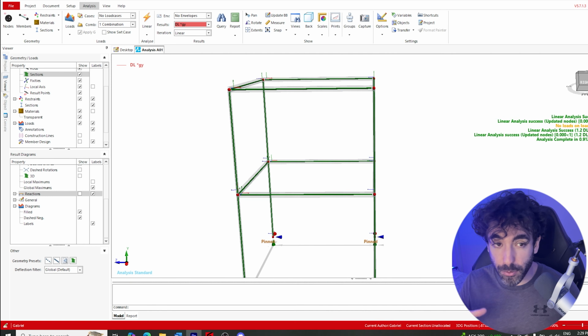It can move into and out of the page, which are situations you don't have in 2D software because it automatically restrains those movements. So you want to catch errors early before you mess up the whole model, and then you have to go back and try to find where you made a mistake. If you're confident enough with releases, by all means, release all the nodes at once and run the analysis.